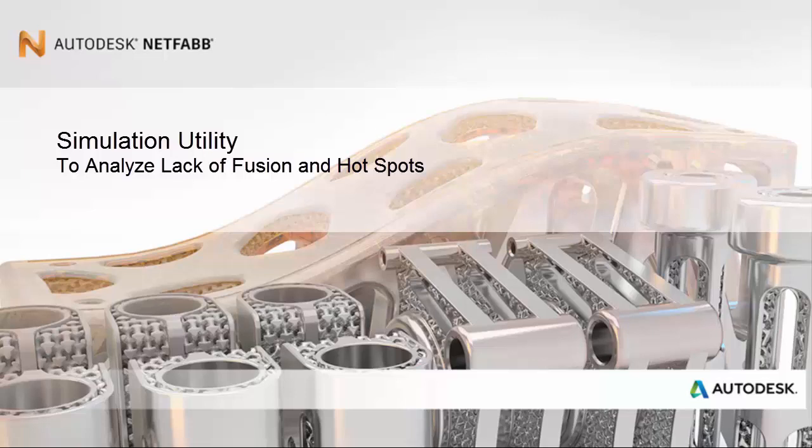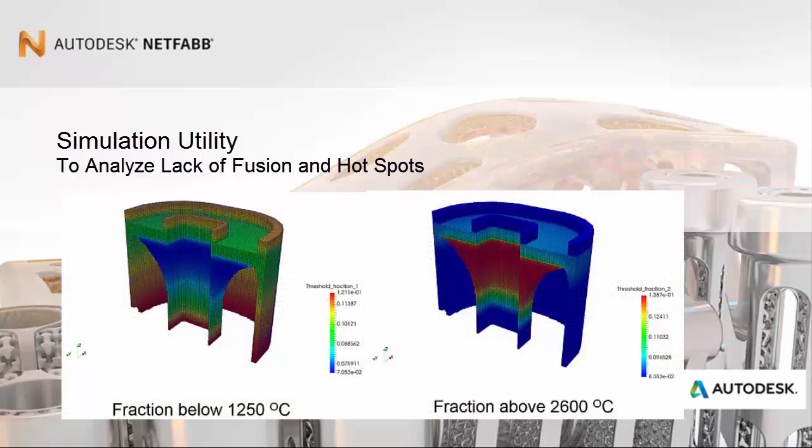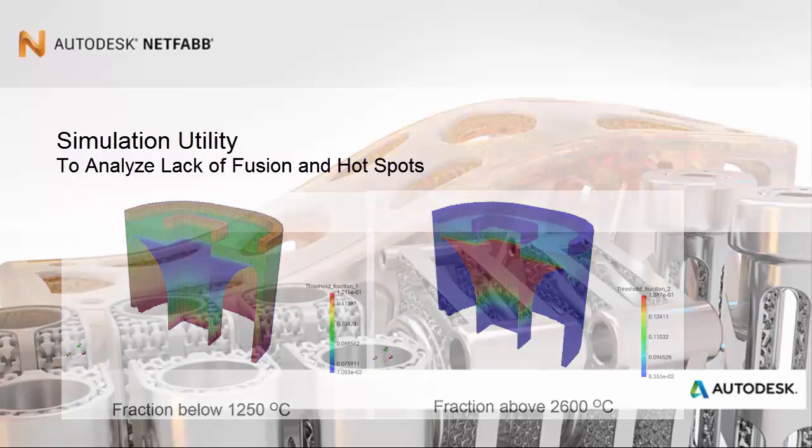Greetings and welcome to this tutorial on lack of fusion and hotspot analysis. As explained more fully in the overview video on this topic, we use lack of fusion and hotspot thermal analysis to identify regions of a build that might not get hot enough to fuse properly, and areas that might get too hot, resulting in oxidation or evaporation of material.